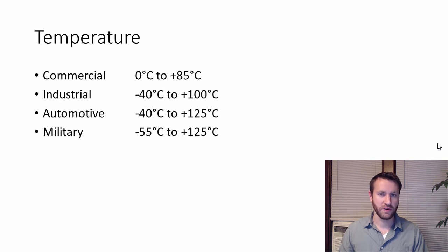Temperature. This, for the majority of you, is not going to be a problem, but it is something to trade. I worked in the defense industry in the United States for a long time, so I was always in industrial, automotive, or military temperature ranges. And military especially is hard to find parts for because it's such a huge range of temperatures, -55°C to 125°C, and -55°C is extremely cold, so that's hard, and that's expensive.